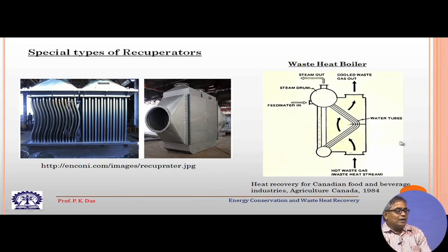This is one typical waste heat boiler, which is also a kind of recuperator, but though we are calling it a waste heat boiler, it is not fired. So, hot waste gas is coming from some sort of a source, and then it passes through these tubes.